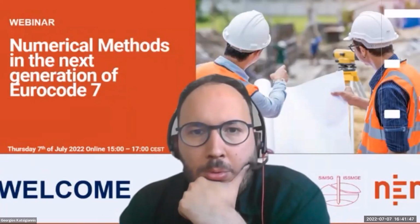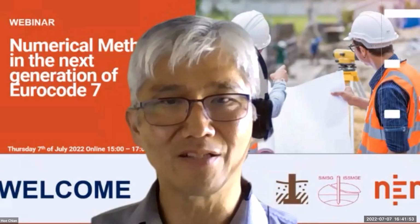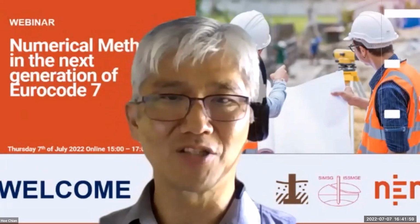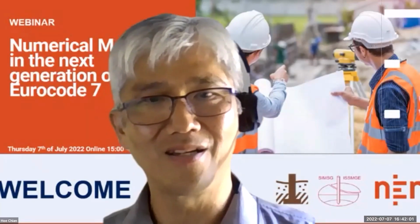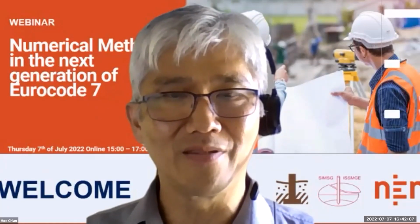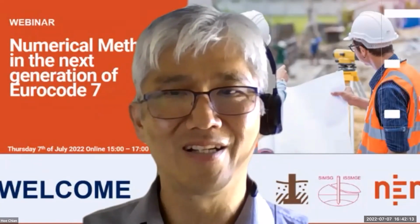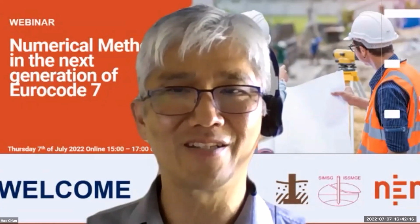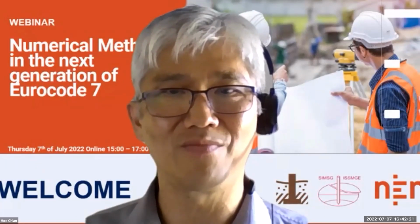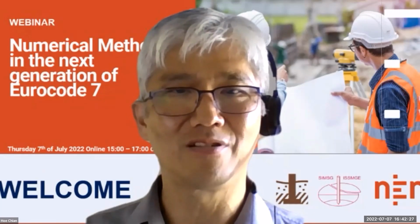Right, there is a question about the two material factor. I think maybe I've not made it clear. The hardening soil small strain model is one type of advanced soil model, and the brick model is a different soil model altogether. I guess the latest version is where you find it in the software. I don't think they have changed much from the two models that I'm familiar with.